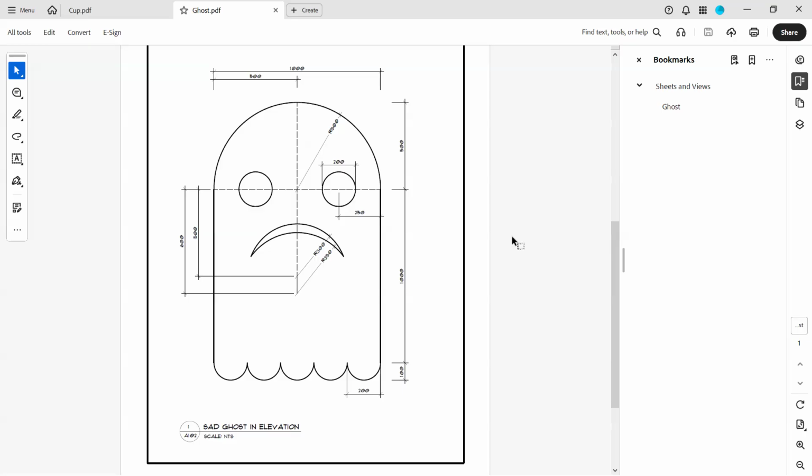DI, if you are not sure, and sometimes I'm not sure, did I do it correctly? You check the distance. DI is the shortcut key for distance. And then you check the dimension from endpoint to endpoint. If you did it correctly, it will show you the number 500, 600, 250. DI. Okay?